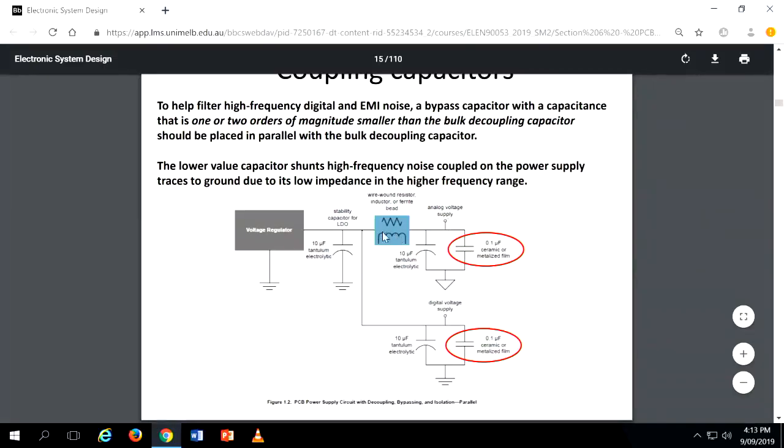Then here they are using a ferrite bead or inductor, because this is connecting to the ICs. Even if some noise is coming, you got the bypass capacitors here with the ICs, but still some noise can come, so this will bypass to the ground. So this also can connect to the ground. This also can act as a local power supply for the analog ICs. Even if some noise is coming here, the ferrite bead will block it, so it will not come here.